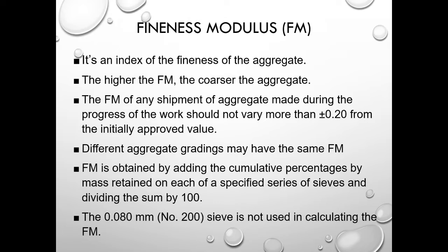An important characteristic of fine aggregate is its fineness modulus. You will be looking at fineness modulus when we're doing concrete mix designs. We need to know how coarse that fine aggregate is when we're designing a concrete mix. It will dictate how much coarse aggregate we need.